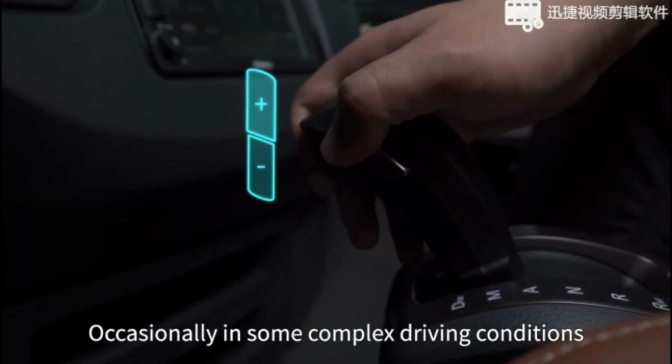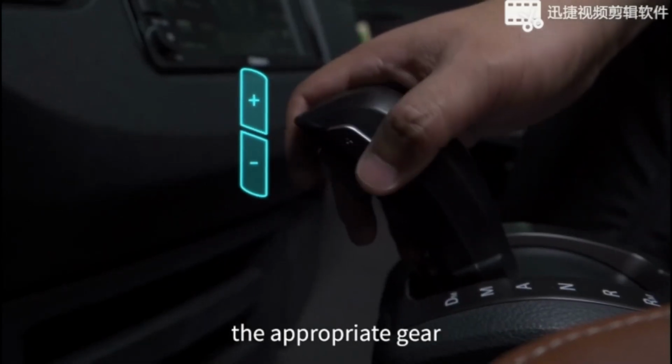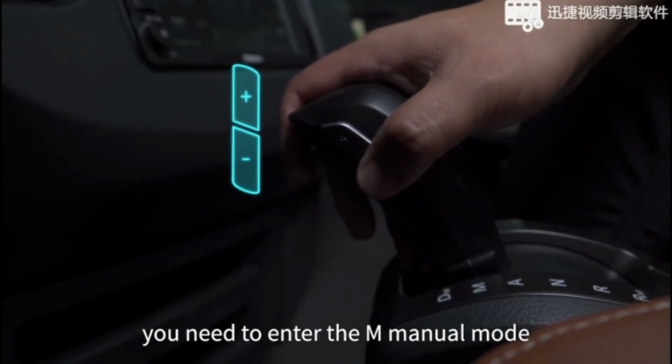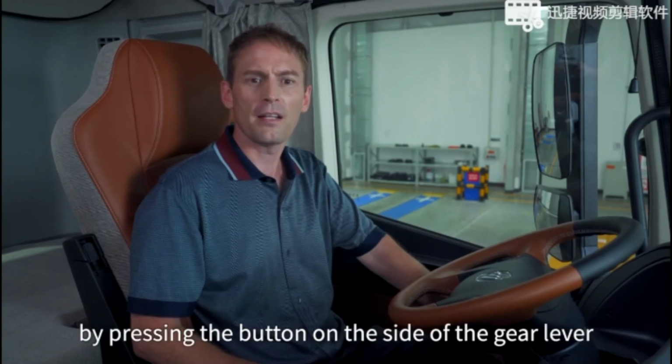Occasionally, in some complex driving conditions, the computer cannot accurately determine the appropriate gear. During this time, you need to enter the M manual mode. In manual mode, you can select a higher or lower gear by pressing the button on the side of the gear lever.